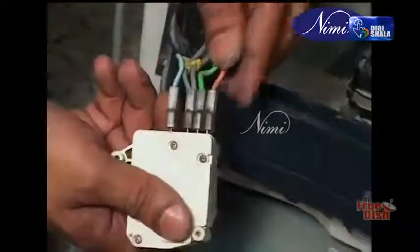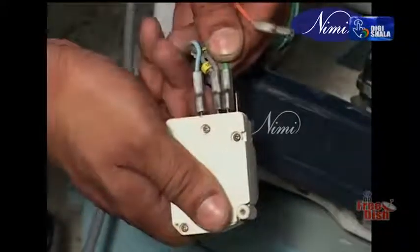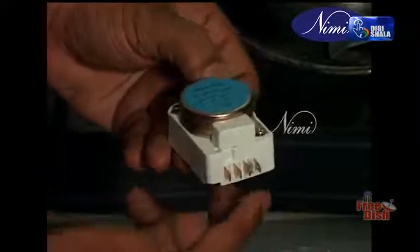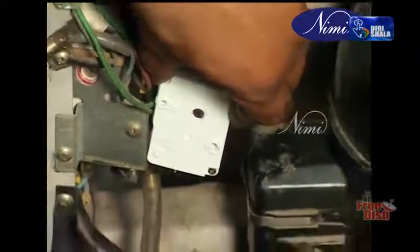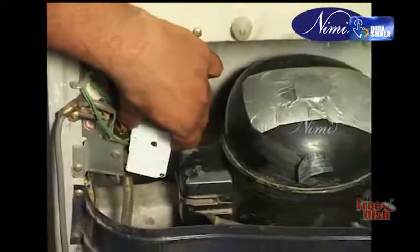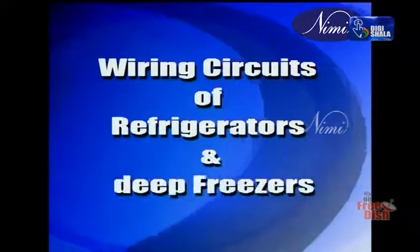The timer switch works on a clock mechanism. When the cooling coil gets over-frosted, by a time of 12 hours, the timer switch cuts off the compressor supply and passes the supply to the heater coil for a set time, say 15 minutes. Again the timer switches off the heater and the compressor starts. Wiring circuits of refrigerators and deep freezers.